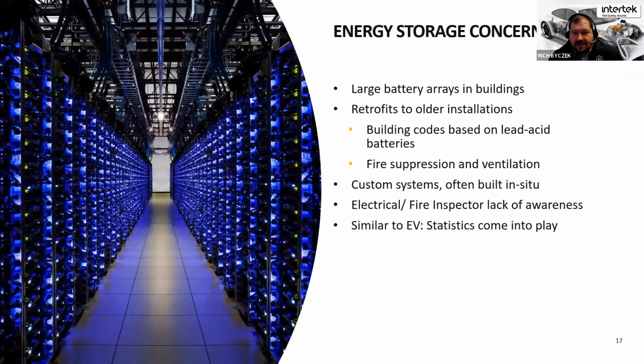Energy storage concerns, we talk about stationary systems, often similar and much larger capacities than we worry about even in the electric vehicle space. These are often retrofits in older buildings. They're in the basement. Something like you see here, an array of batteries that a few years ago was all lead acid, and all you were really concerned about was having enough ventilation so that during normal charging, any hydrogen off gas could not build up to create an explosive atmosphere.